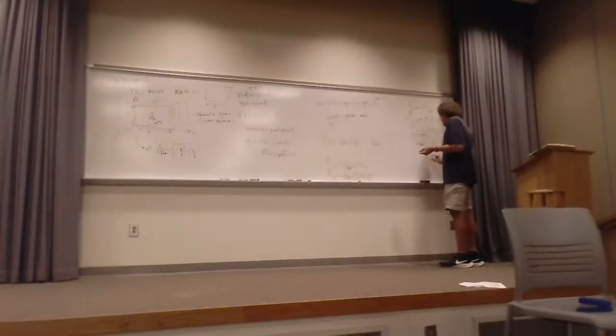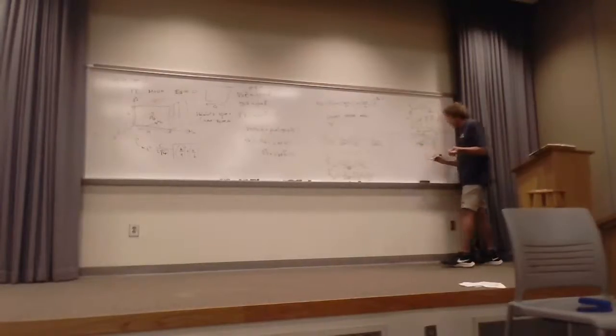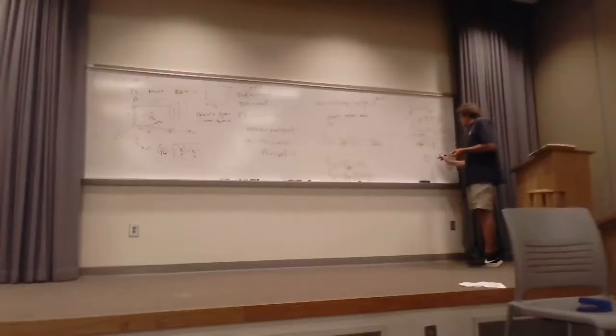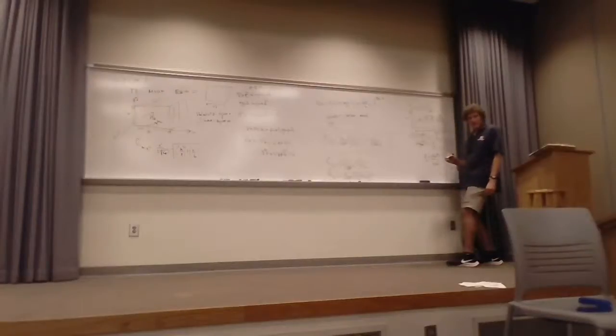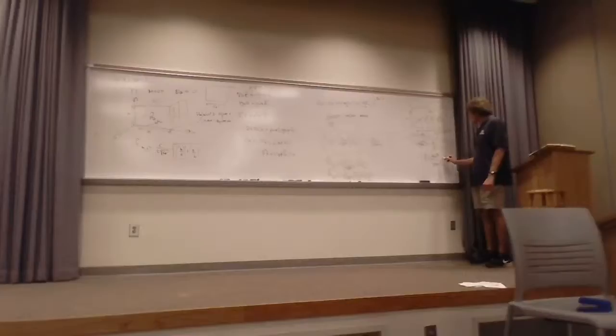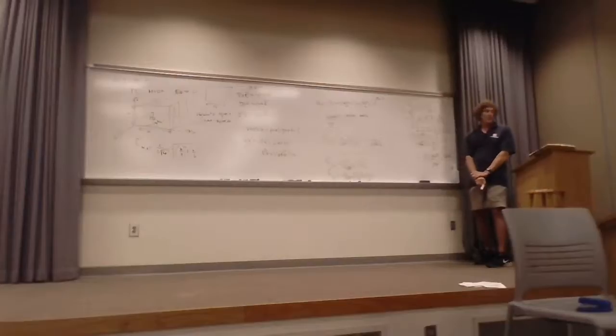What is the frequency going to be for the 1-0 cutoff? Well, I would take C, which is 3 times 10 to the 8th meters per second, divided by 3 times 10 to the minus 1, right? Correct? What do I see? The 3's go away, I get 10 to the 9th, or it's going to be 1 gigahertz would be the cutoff frequency for the 1-0 mode.